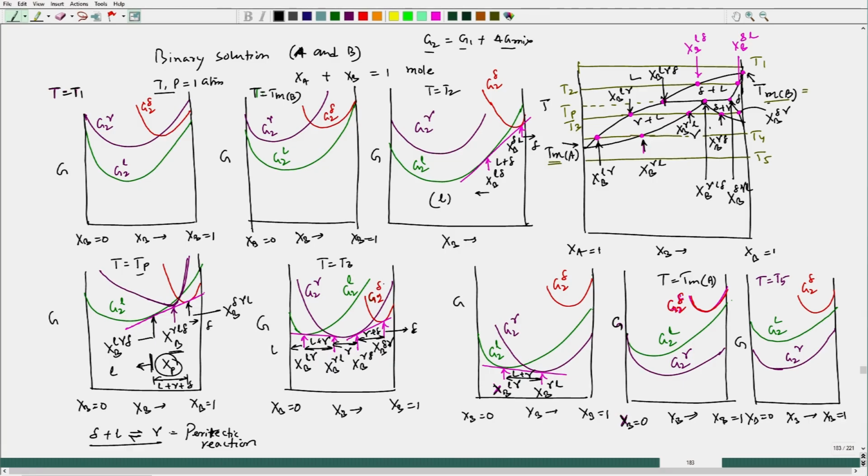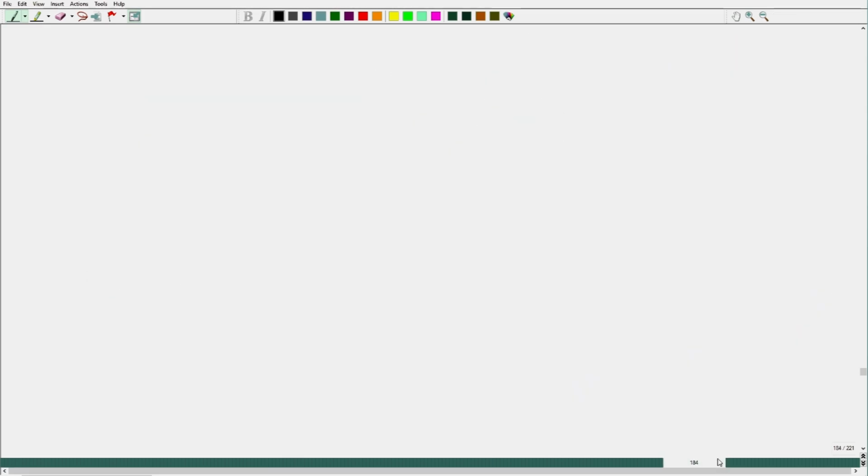As we have seen, we have to see the dotted lines which are reflecting metastable compositions, and those metastable compositions, if we had seen in case of eutectic as well as eutectoid, in all cases are actually entering into the two phase zone. Let us see that part, whether the phase diagram is drawn correctly or not. In order to judge that, you can take this metastable composition marked in the phase diagram. For example, in case of eutectoid, rather we started with eutectic, x b this way, x b equal to 1, x b equal to 0, and let me just draw the eutectic one first.